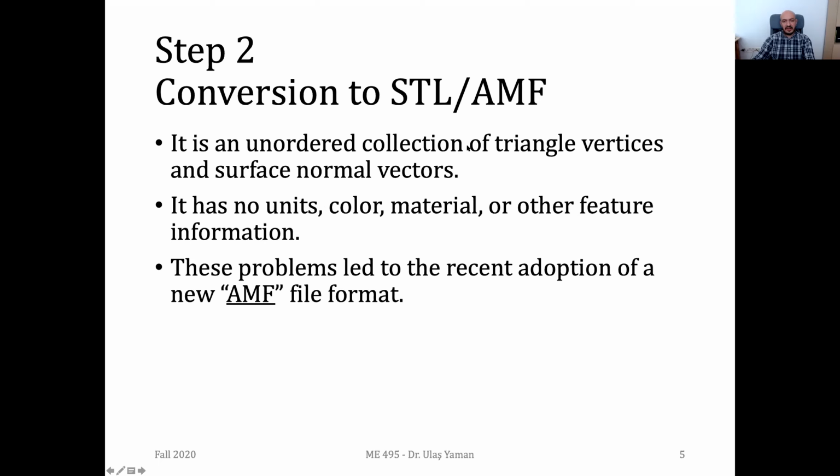And since we have these difficulties and problems in the STL file, that's why people are working on another format, the additive manufacturing file format. In that format, they want to include such information: the color of the product, the unit, the material of the product, and also sometimes the design history. How you designed it, you did first extrusion and then cutting, some joining operations, subtraction operations. These will be stored in the additive manufacturing file format.